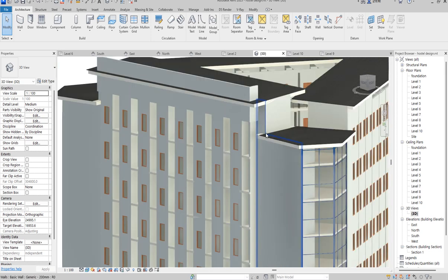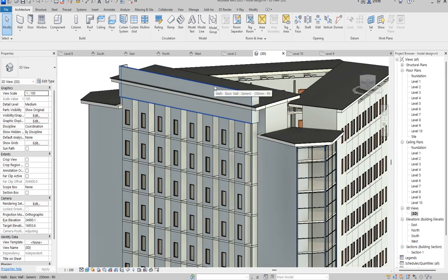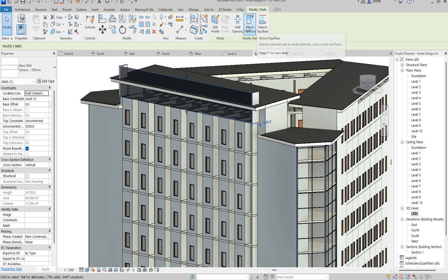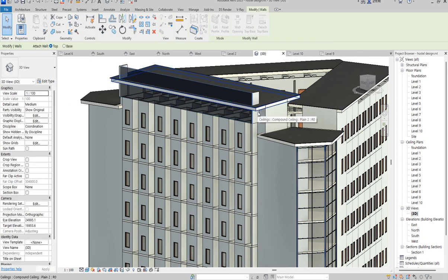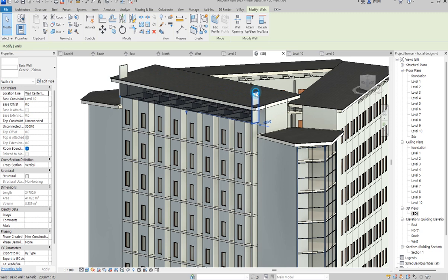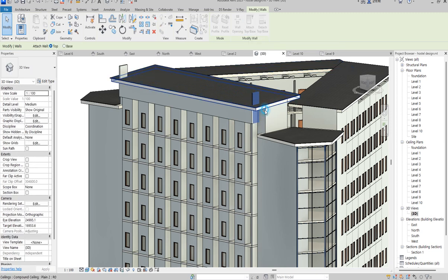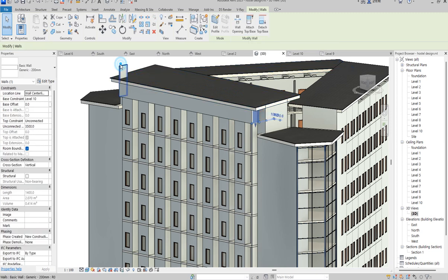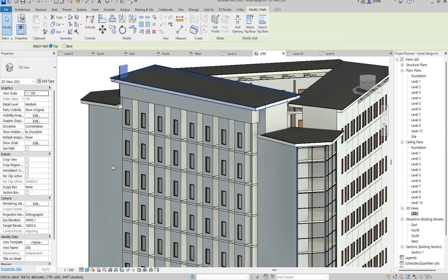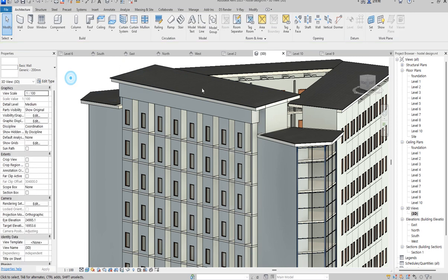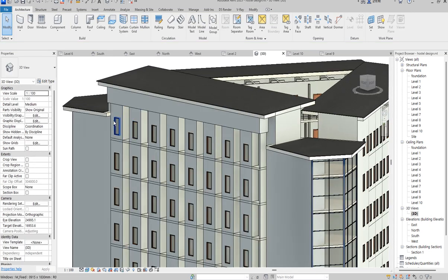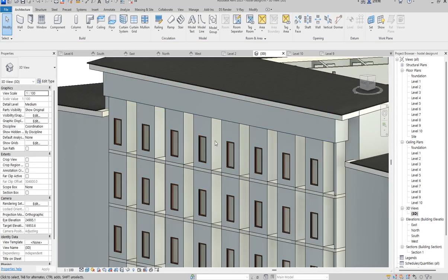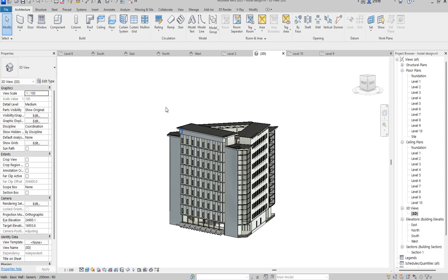So this one now covers up to some level. I'm going to do this by saying select this and align, attached to the ceiling. So that will attach itself to the ceiling. Do the same thing to this one, attach to the ceiling. Do the same thing to this one, attach it to the ceiling. So I have this in place. Then we continue with this, we are going to do the whole adjustment. So now I want to bring the beauty of the design.